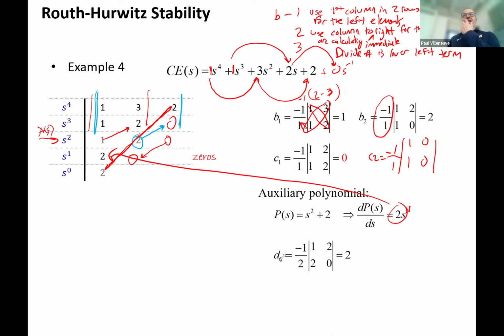What did Garrett just say? Could have one j omega. Look in the right-hand half plane. Yeah, the rule is it tells me how many poles are in the right-hand half plane. It doesn't tell me that all poles are in the left-hand half plane. It just says here that none are in the right-hand half plane. So it indicates that it's not an unstable system, but it doesn't guarantee it's a stable system because it could be a marginally stable system.